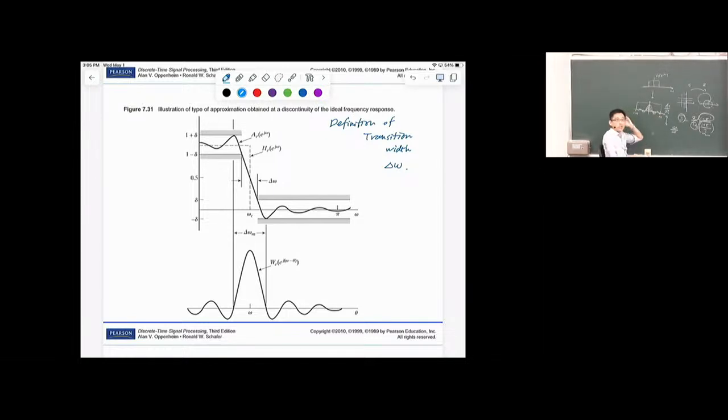So it turns out that we just learned when M increases, when the length of the window increases, then the height of the main lobe increases with increasing M, while the width of the main lobe decreases with increasing M. So it's growing taller and narrower when we increase M. And increasing M means keeping more of the middle samples, which is usually desired. In what sense? In that its frequency response is becoming more and more ideal. And that makes a lot of sense.